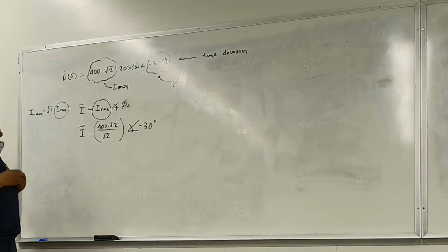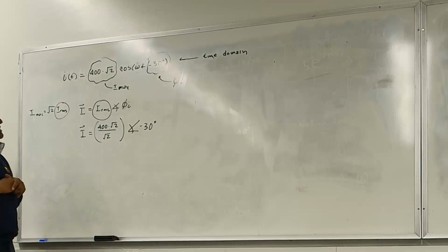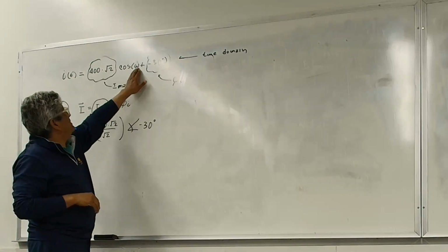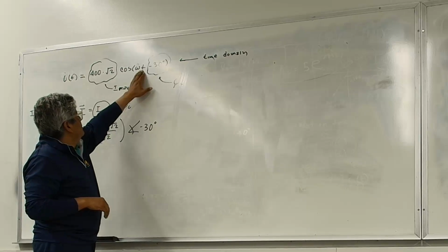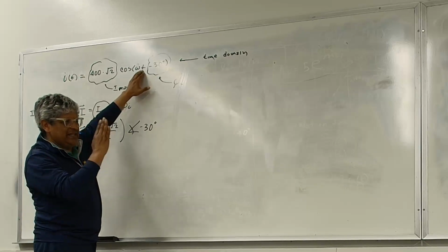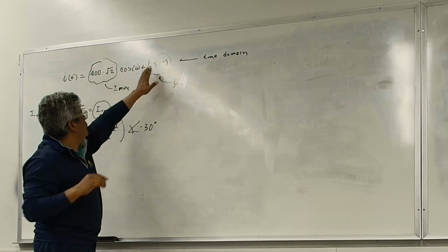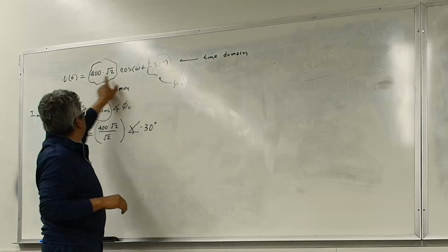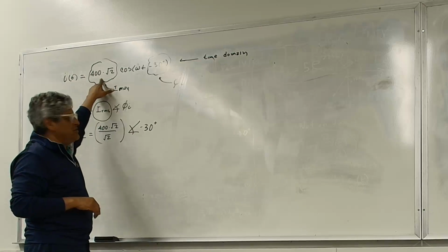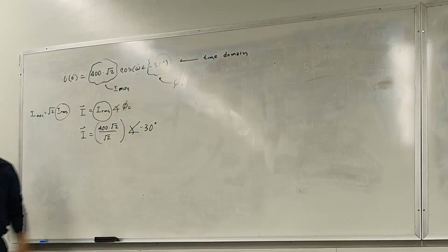Another way you can see it, and I probably didn't explain it that way, is if I make this t 0, that's what I'm freezing. I'm freezing this signal when t is equal to 0. This becomes 0, so I got this angle and this magnitude. The only thing I do is divide it by square root of 2 to get the RMS value, right? That's really what it was.